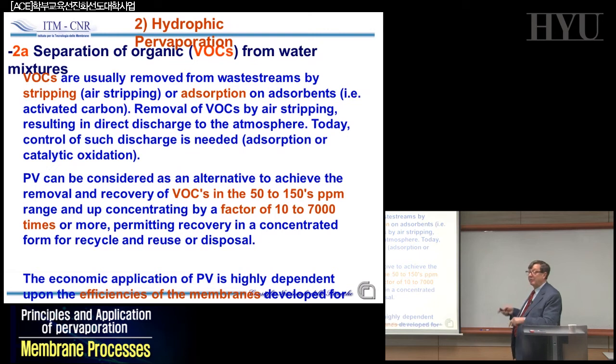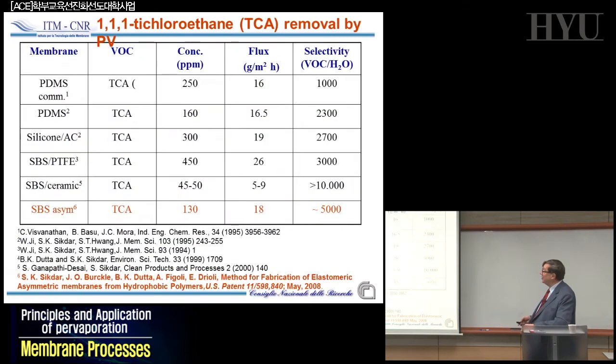So membranes similar to PDMS. These compounds are normally present in a very, very low amount. So the best is to have a system in which you can remove them. You don't filter the air. You have to remove the contaminants, which are a few ppm. So if you have a very selective material that can do the job, you can have quite interesting contracts to develop this kind of system for the VOC removal at very low numbers. Here it is 50 or under 50 ppm, but sometimes you have a concentration factor that has to be very, very high. But it is a scientifically very, very interesting system.